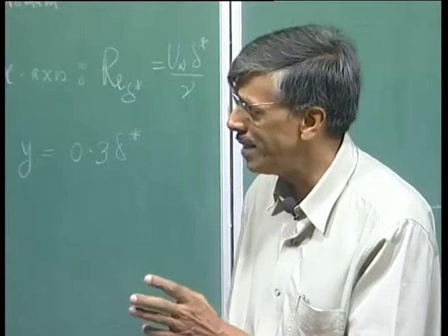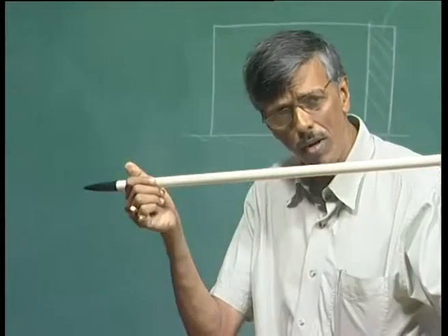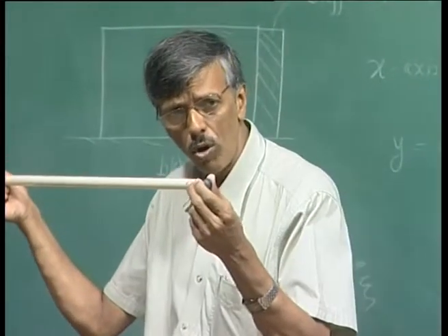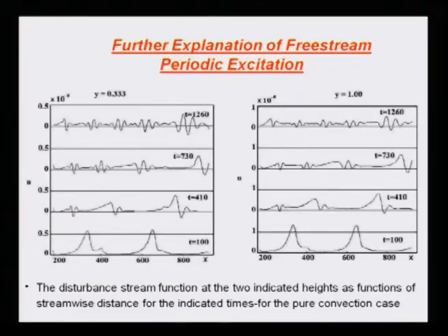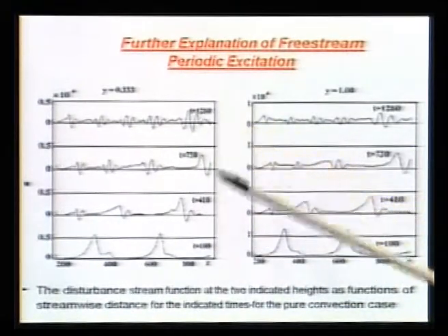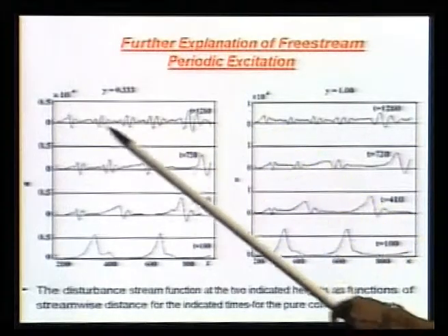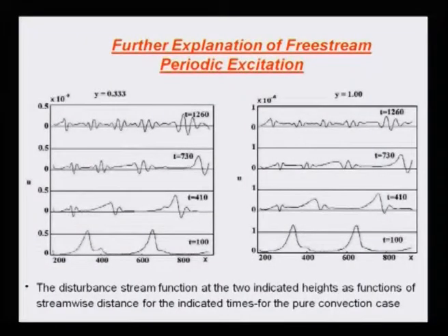So, what in a sense we are saying, that even though you allow an inviscid vortex to go to begin with, it will be pretty harmless, but with the progress in time you are going to see that it is going to fill up all kinds of length scales. You can take this solution and do an FFT, and you will see that it is quite a wideband phenomenon.